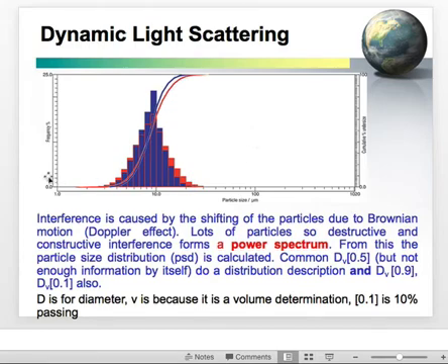And we often do a D90, a D50, and a D10. Often that's called the DV 0.5. The D indicates diameter, the V indicates that we're doing it by volume. So we're not counting the number of particles, we're saying these are the contributions by volume in these particular sizes. Obviously if we went by area or by number, there would be a considerable shift.